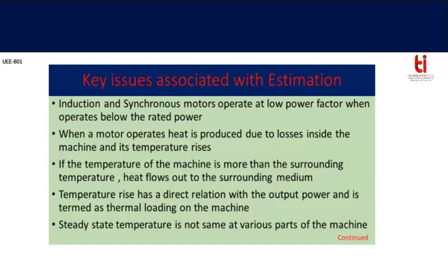Key issues associated with estimation. First of all, we know that when our most popular motors, induction and synchronous motors, operate at a power less than its rating, then the input power factor becomes poor. Because of that, current drawn from the source consists of lots of harmonics. Efficiency of the system reduces. Complete behavior of the system is changed, or the system becomes costlier, filtering requirement will increase. So those issues are there. So our induction motor and synchronous motor must operate close to its rating.